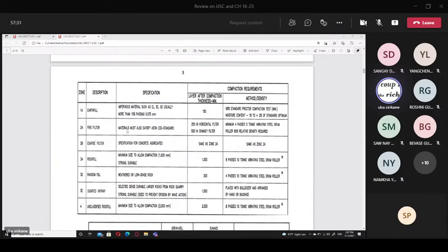For fine material, in horizontal or vertical chimney, we call it chimney filter. The material must satisfy the ASTM C33 standard. It means a kind of fine aggregate for concrete, like sand without fine material. You see, quartz is also concrete aggregate.